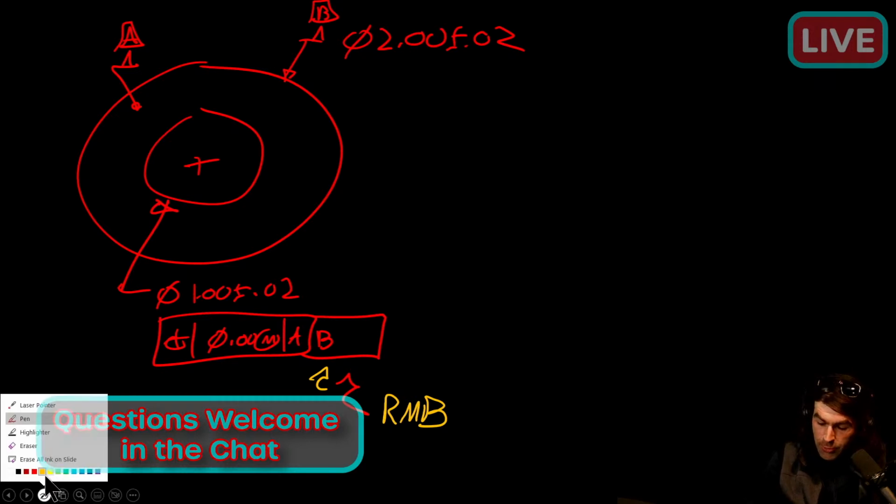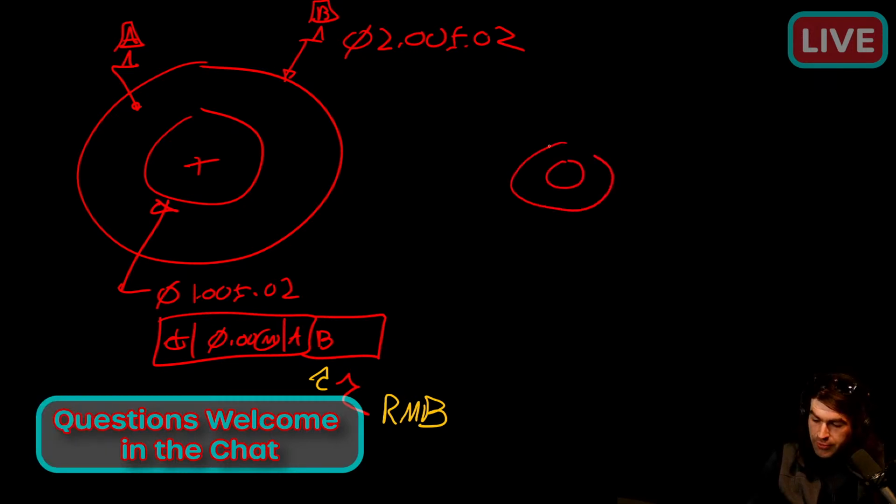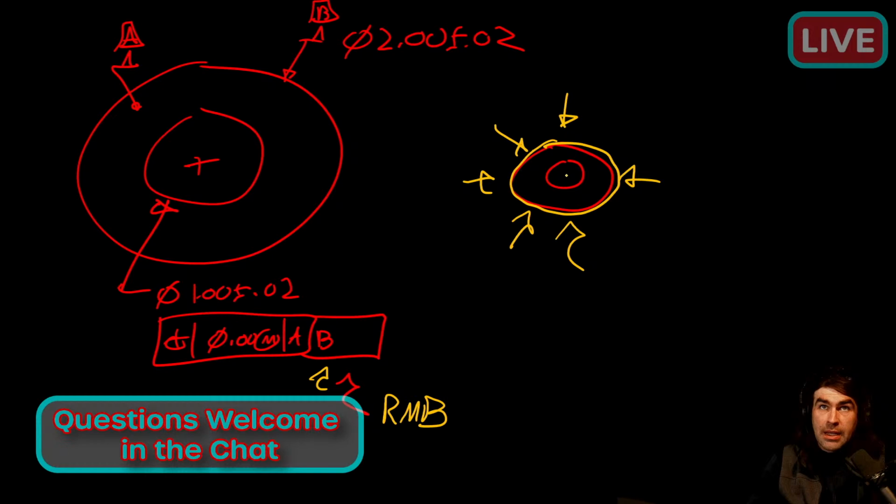So when we go check our donut, here's a little version. We've got to capture it in some kind of thing, a chuck or a collet or whatever. We've got to have some way to restrain it. And whatever collet or chuck is going to have an axis, and we're going to compare that axis to the axis of the donut hole. If that sounds like a lot, we could use the MMC symbol and modify it at maximum material boundary. And what that does for a donut,